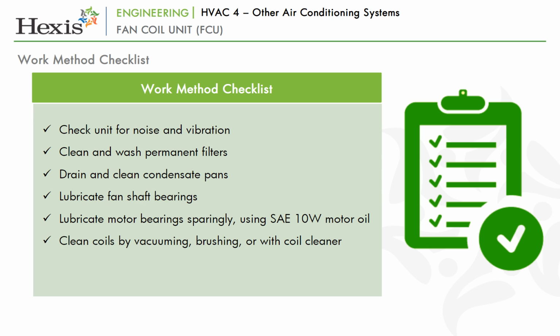Clean coils by vacuuming, brushing or with coil cleaner. Use fin combs to straighten coil fins. Clean strainer ahead of unit.